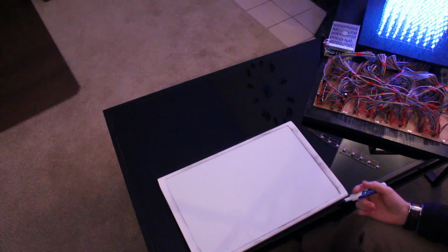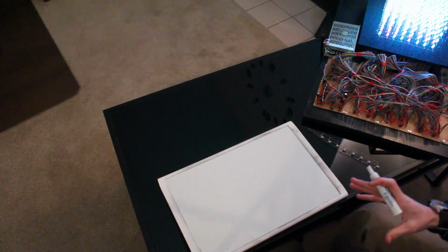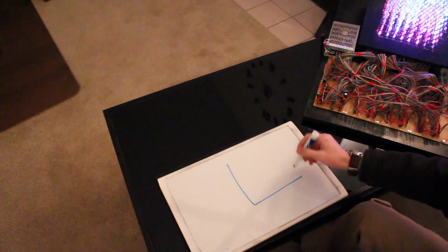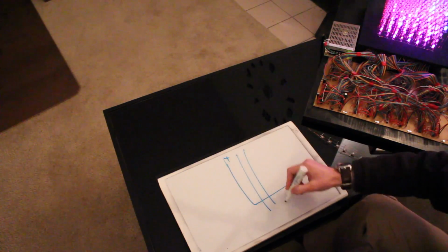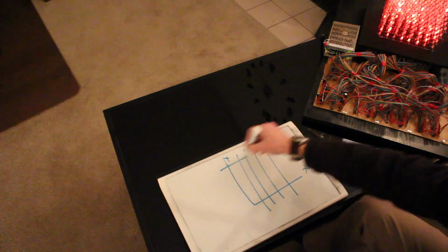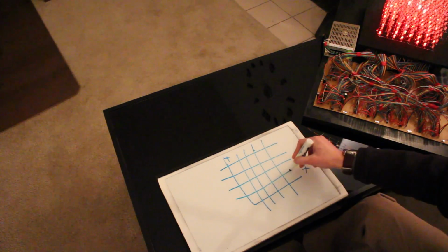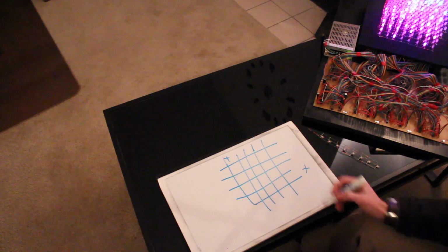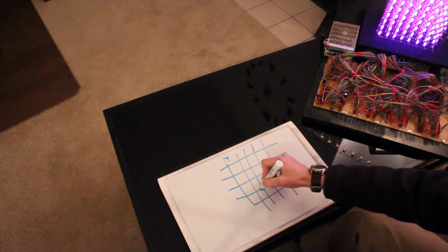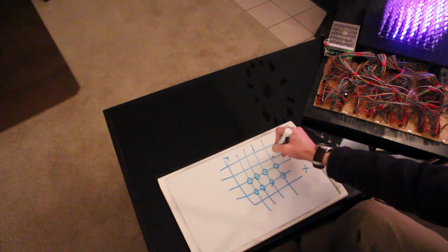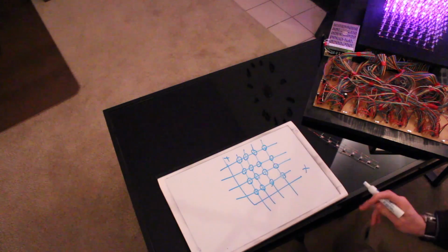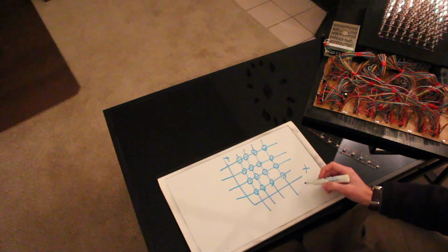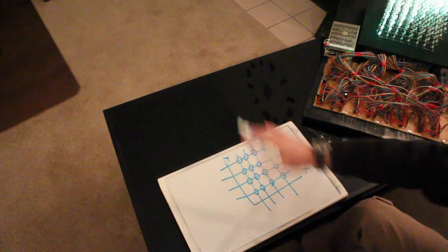Now let's take an example of how to control a lot of LEDs. And you usually go back to the grid topology. So if you have a grid here, it's kind of like an XY type of grid, and I'm just going to take a 4x4x4 here. And yeah, it's not exactly how the cube is, but we'll get to all that. So we build up a grid where all the intersections are an LED. These are just single color LEDs, not RGBs yet.